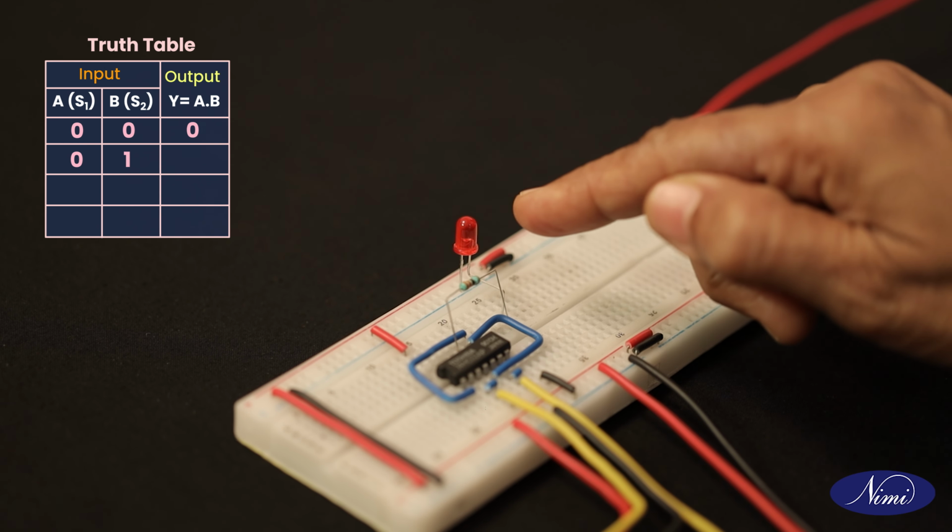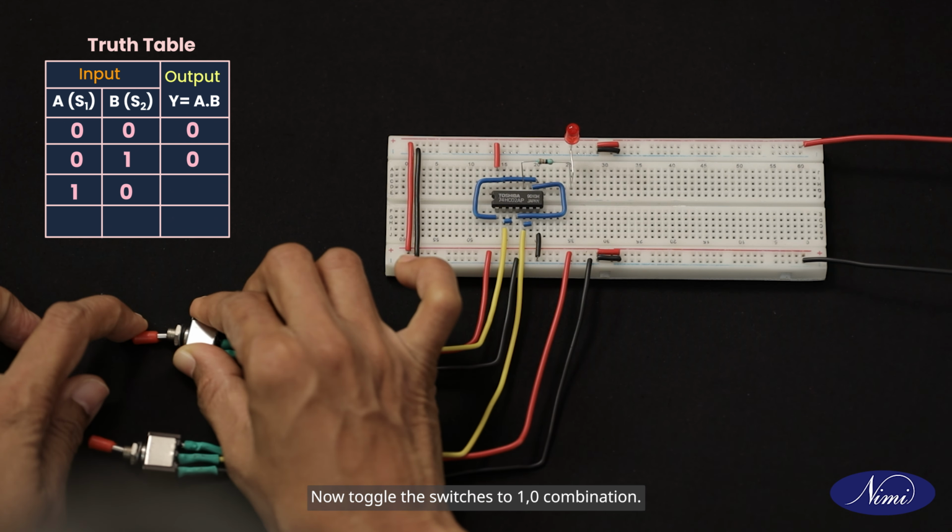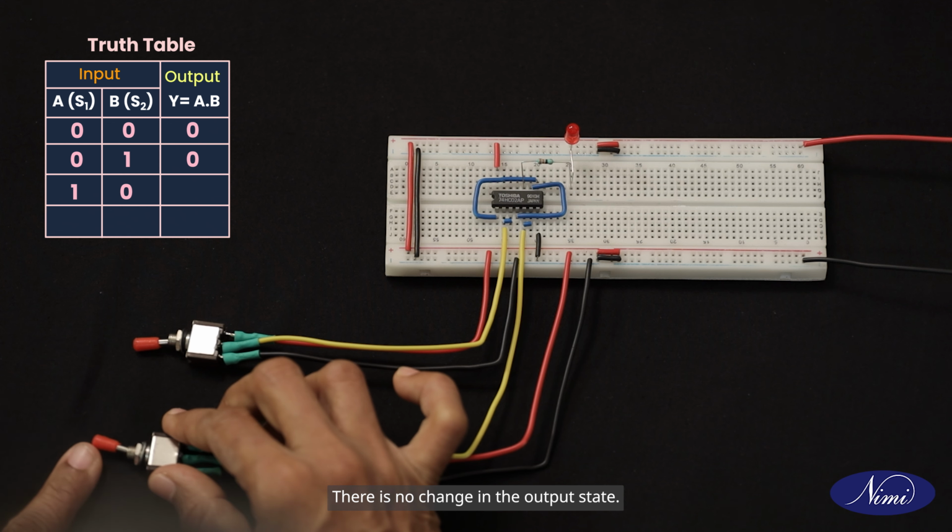Verify the LED. It is still not glowing. So we know that if any of the input is 0, AND gate produces the output 0. Now toggle the switches to 1-0 combination. There is no change in the output state.